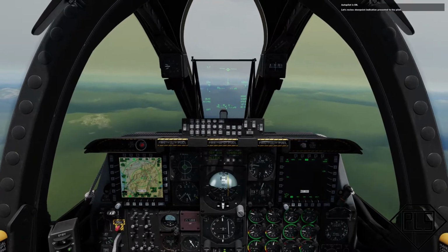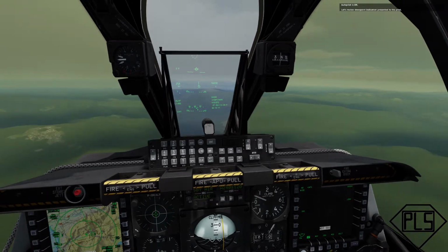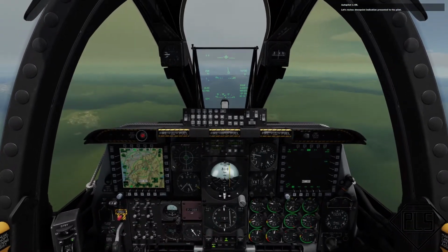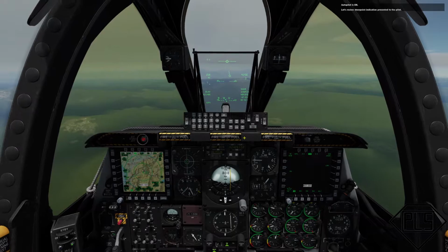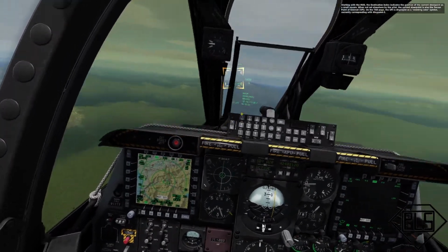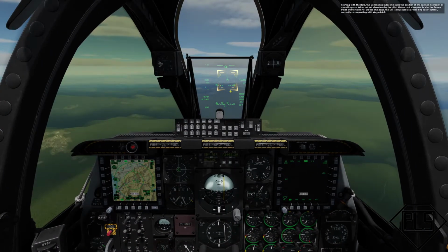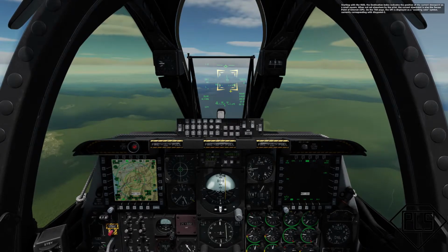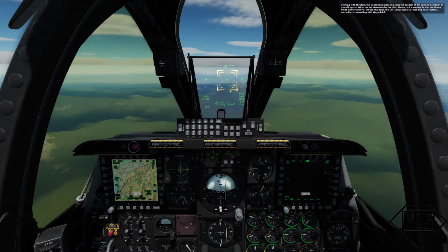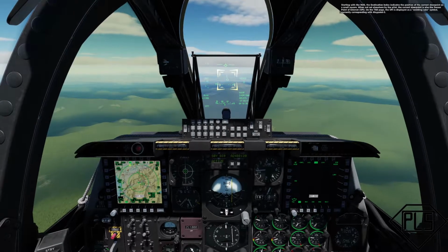Autopilot is on. Let's review steer point indication presented to the pilot. Starting with the HUD, the destination index indicates the position of the current steer point as a small square. When not set elsewhere by the pilot, the current steer point is also the central point of interest, SPI. On the TAD page, the SPI is displayed as a wedding cake symbol currently corresponding to waypoint 3.